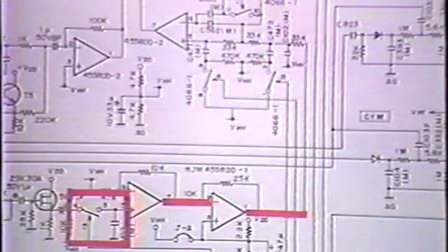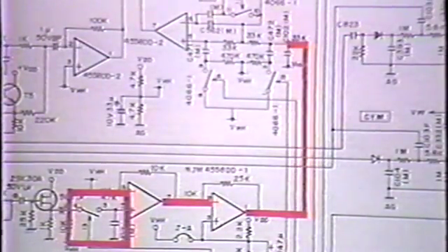When glitches do not occur, the switch is on because the 25 kHz pulse is high and the digital to analog converter output passes the switch and charges the capacitor. The 25 kHz pulse is low when glitches occur, therefore the analog switch is turned off. Consequently, the digital to analog output containing the glitches cannot pass the switch. The capacitor then discharges, maintaining the sample and hold circuit at the same electrical potential. In this way, the sample and hold circuit eliminates glitches. The glitch-free digital to analog converter output next enters the filter block.